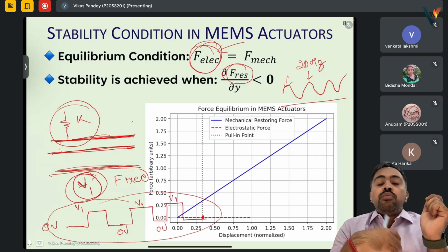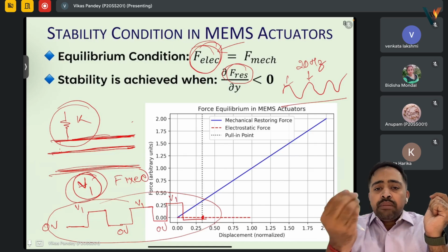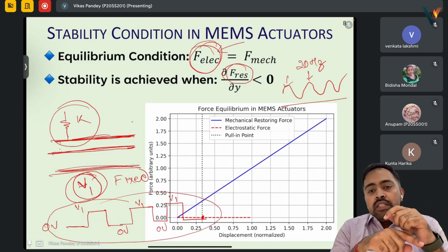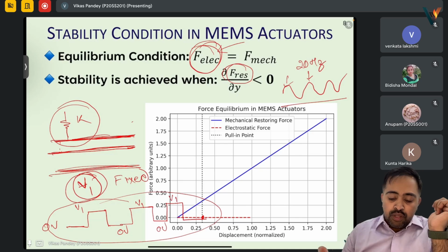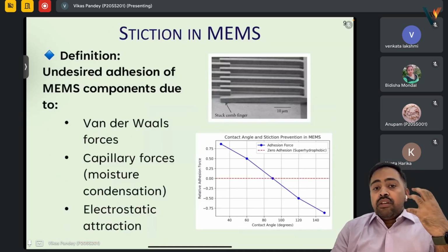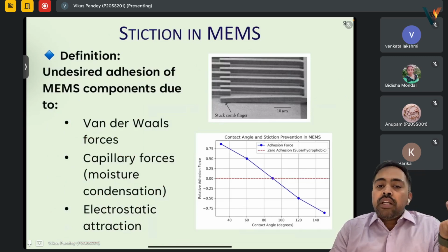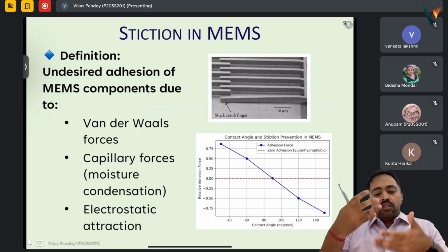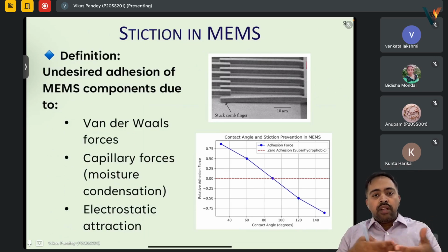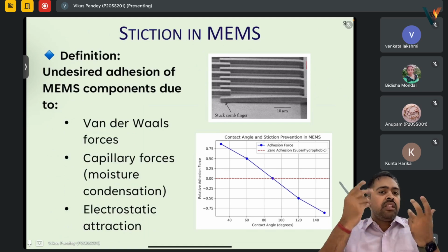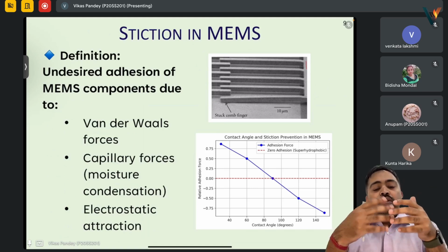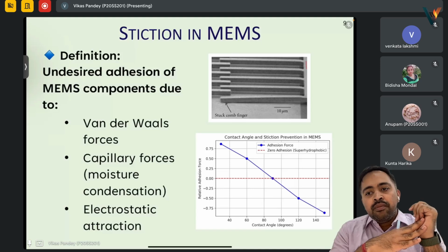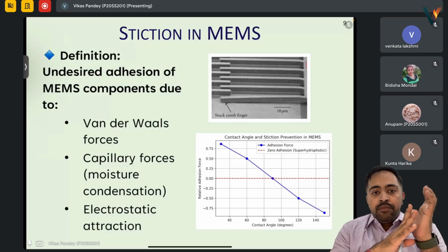And as such, we are able to create a lot of MEMS resonators. MEMS resonators are one of the very common devices made using MEMS technology. Okay, then we saw how this movement can be created. Suppose that we want this whole structure, this comb kind of structure, to move continuously. And due to this movement, there will be a humming sound, say, or due to this movement, we are switching on and off some circuit. Okay, such things can be done.